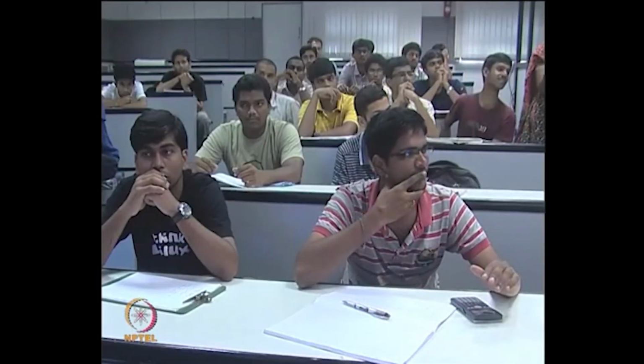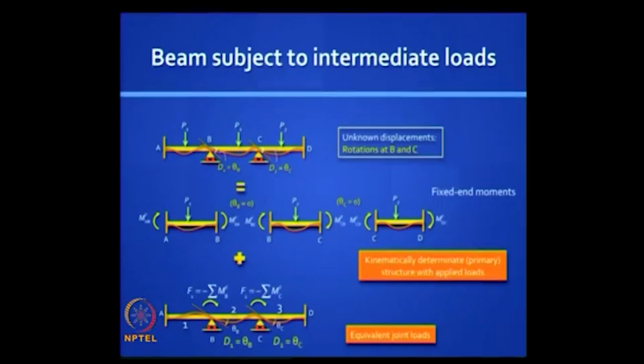So you can do this. Go back to the old beam. Apply nodal moments F1 and F2, which are the negative of the moments that accumulated there when you artificially arrested those rotations. Now does this make sense?